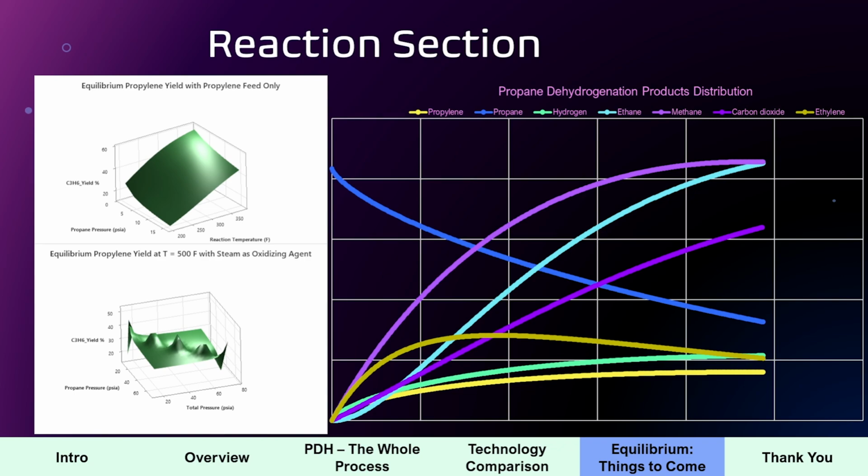So these are the problems that arise with thermodynamics versus kinetics, at which point the thermodynamics delivers a milestone to move to the next step. And at which point you find something in the lab, you run an experiment, that makes everything you have done thermodynamically speaking invalid, and you're going to need to do trial and error or iteration. You're going to need to go back to the same function that you had done previously, that assumed a single reaction, and run the same thing again to find out how the chemical equilibrium is going to look.